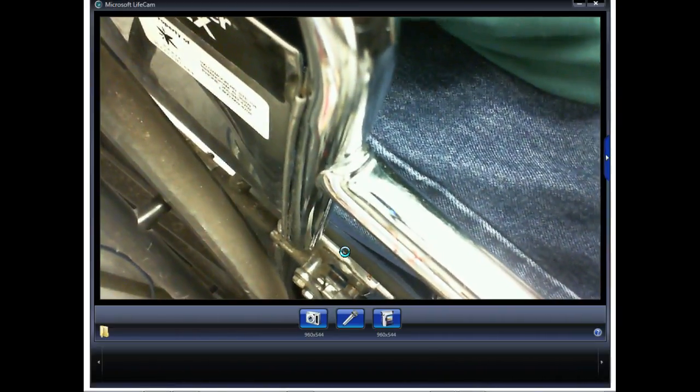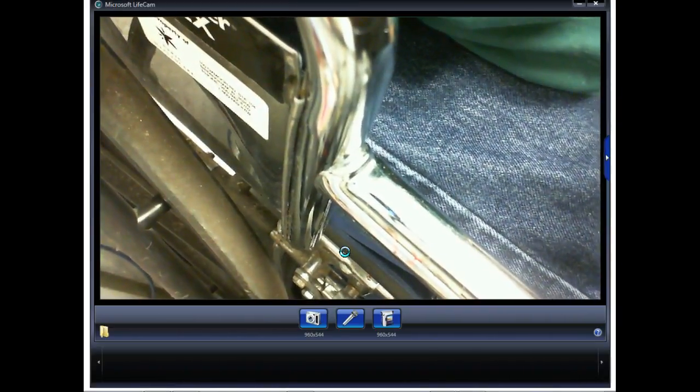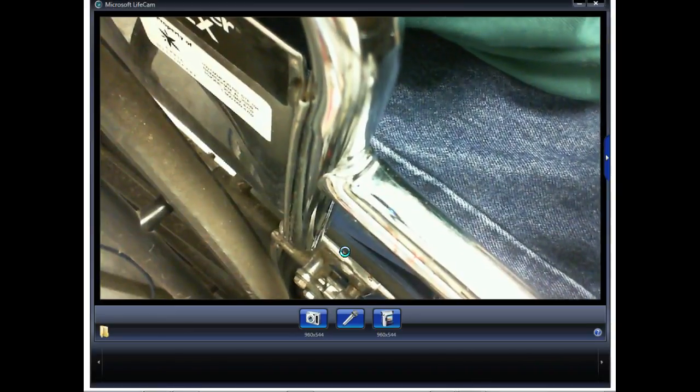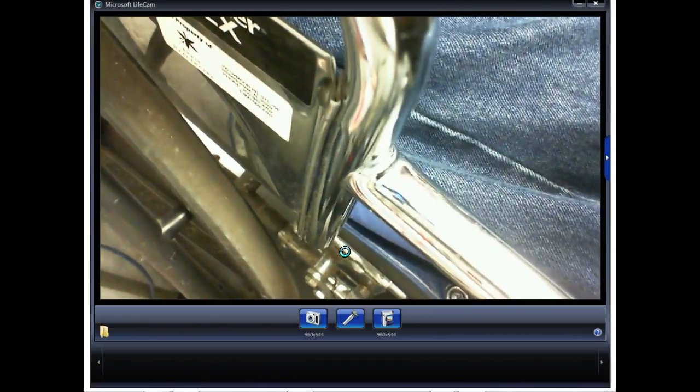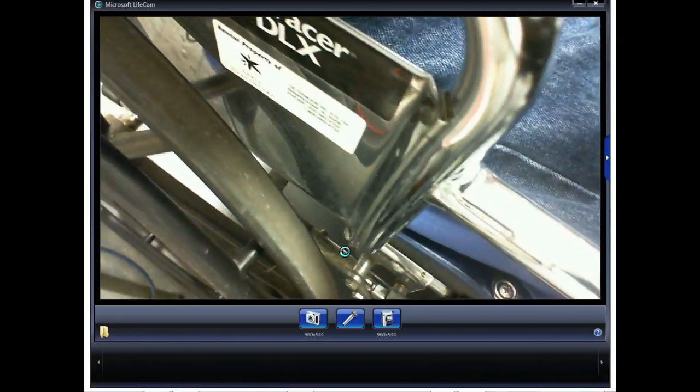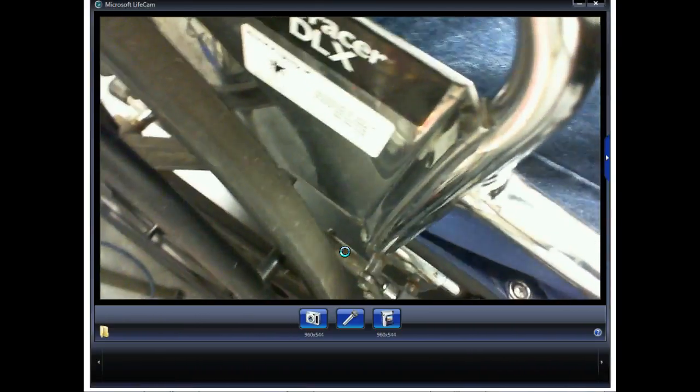So this is the kind of stuff I want to see. I want to see what? I want to see these pin numbers on the schematic before you wire them. Does that make sense? And then once you've got them on the schematic, it makes it real easy to do what? To wire it up. So now you're not going between two documents trying to figure it out. You're going to one document, right? Y'all understand that? So first thing you're going to do, and that's in the procedures, is assign pins.